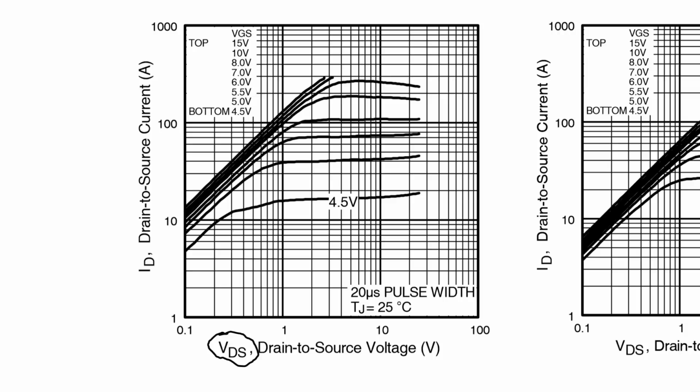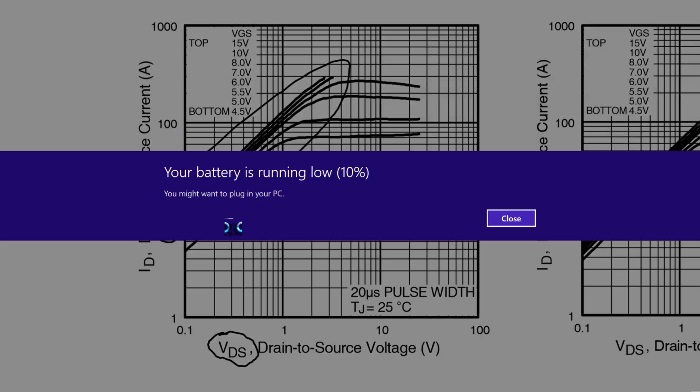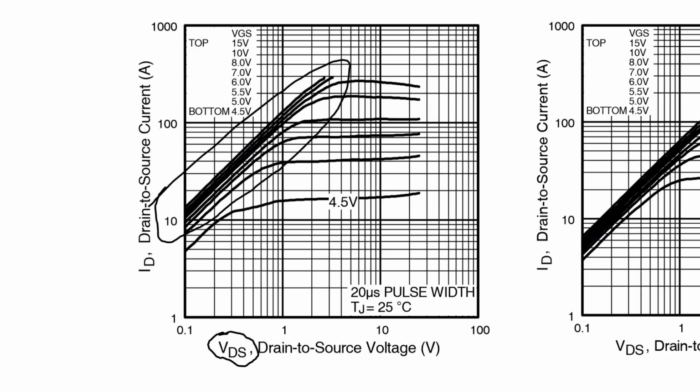And the reason that they're often given as a resistance is if you look at this area right in here, unfortunately it's going to come in black, but see how those lines, especially the ones up towards the top, are basically straight, right? And because they're straight, it acts like a resistor, because the voltage to current relationship on a resistor is also straight. Voltage equals IR. And of course this is a log-log plot, but it's that straight business that they're emphasizing here.